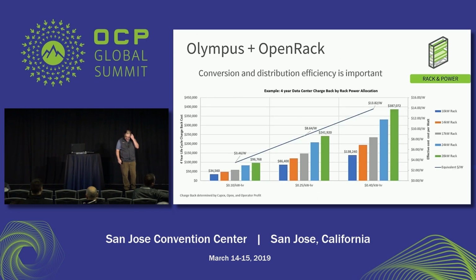If you look at this graph, I've made some guesstimates here on what an equivalent penny per kilowatt hour would be. And a lot of this depends on where you are in the world, your tax structure, the feature set delivered and purchased in that colo. But on the low end, you're at 10 cents per kilowatt hour. That's not too far above what some people pay in the home. So that's a pretty low price. That's a pretty slimmed down design. On the right-hand side, you've got the more feature set, dual cords, highly available 5 nines type data center. And that's pushing 40 cents per kilowatt hour in my best guess.